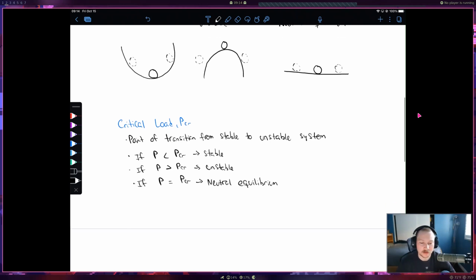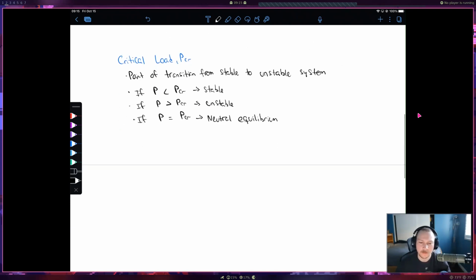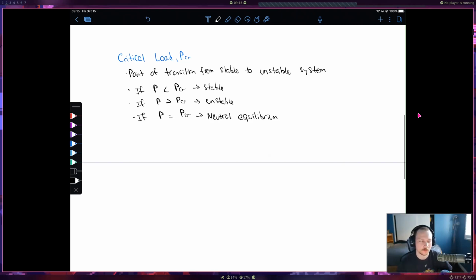Okay, so there is an equation for this, which is the Euler buckling load equation. But this is only going to be applicable for what we call "long columns." That's in quotes here. So we still need to define what makes a long column versus a short column and an intermediate length column. We'll get to that in a second. But this equation, this Euler buckling load equation, is for the critical load for long columns.